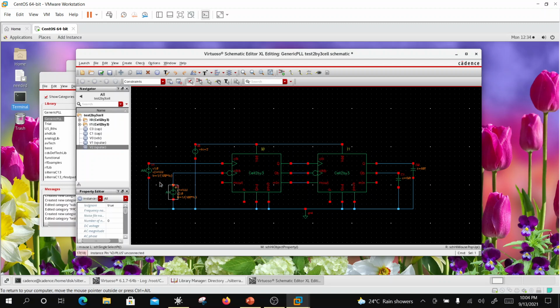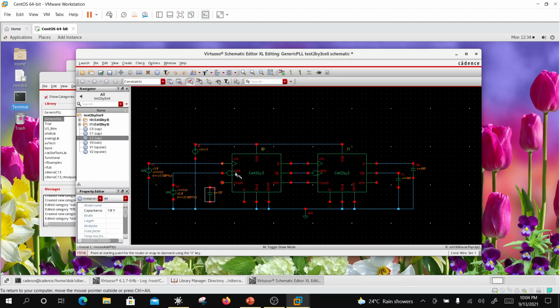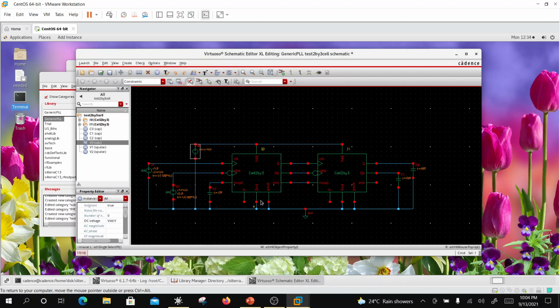Let's see. Okay, so we are now in tandem, and here I'll put a 10 femto. Actually, it should be floating, but let's terminate this, this is the final mod out. I'll make this a 10 femto because it's just one transistor inside the design. Okay, so that's a 10 femto, and this one I'll call VDD. Okay, so we are in business.